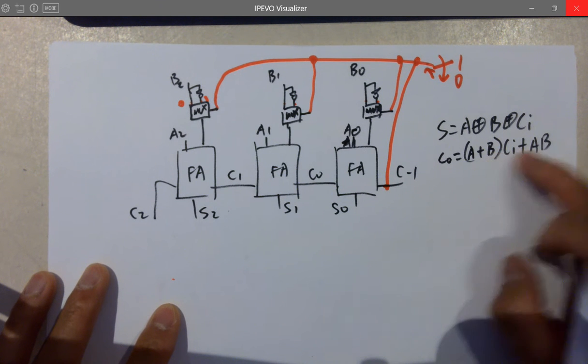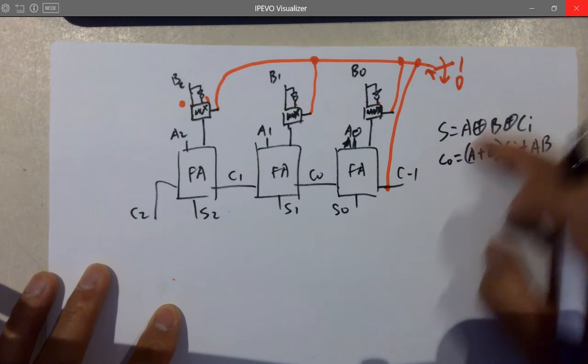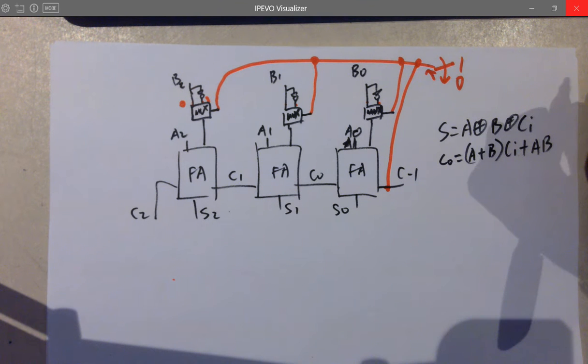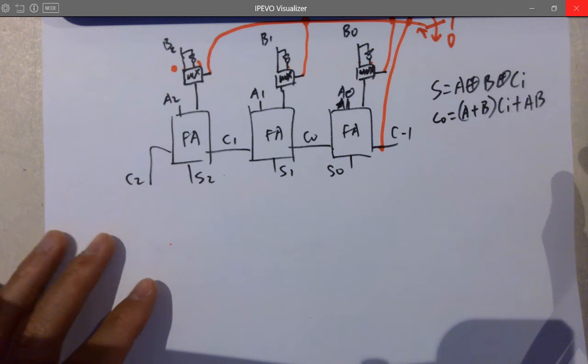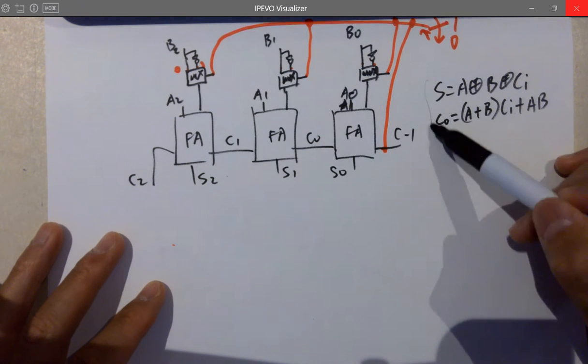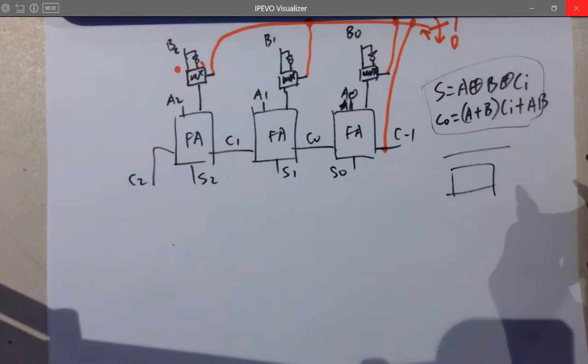Not to mention this one, but also the XOR gates have a lot of gates in there. It's a lot of time delay, which can make the operation pretty slow. So I want to design a high-speed full adder out of it using the complex CMOS logic. And remember, the starting point is you still have to convert the logic expressions to something underneath the bar, right? Remember?